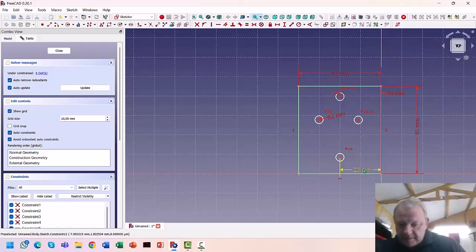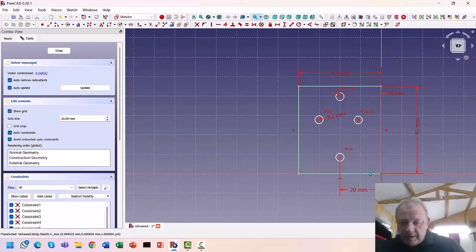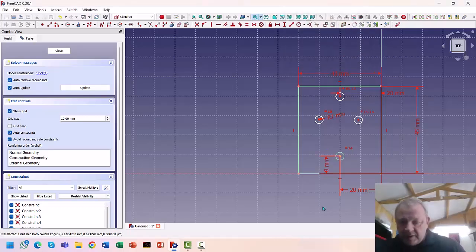Okay, so next we are going to move this one up there, and the distance from the bottom of the C channel up to the center point here is supposed to be about 9 millimeters. So we're going to have to set it from there to there at 9 millimeters. Okay, so we've got 9 there. That's fine, that worked just great for us. So let's move that one. So this point is 20 horizontal, 9 vertical. Okay, that's number 1.